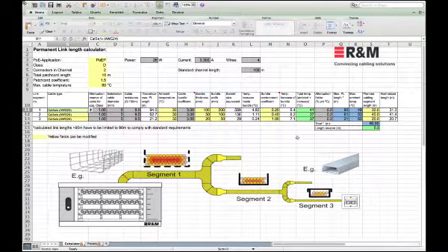But the thing now is we start "what if". So if we say, for example, instead of PoE Plus, we want to have a 4P PoE with 100 watts. That's the worst case that we could have. Now we see the effect of the 4P PoE. We'll see that with the same installation used with a different application, we'll have some serious problems. For example, the maximum temperature of the copper will exceed the limits dramatically.